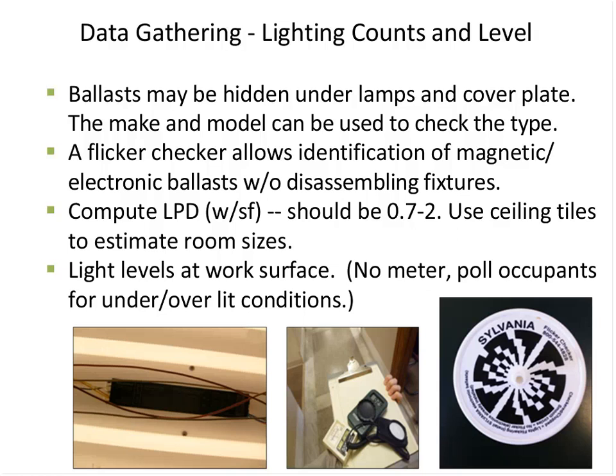And if it's all smooth gray circles, that tells you it's an electronic ballast. If it's a magnetic ballast, you're going to have little flickering going on in there. And it's going to be sort of bluish or yellowish and gray flickering going on. That tells you it's a magnetic ballast. So you know that those need to be replaced. And actually, I think right now they're not supposed to produce magnetic ballasts anymore.